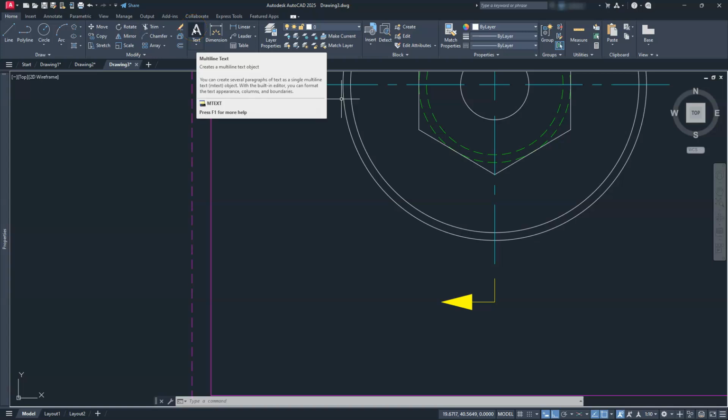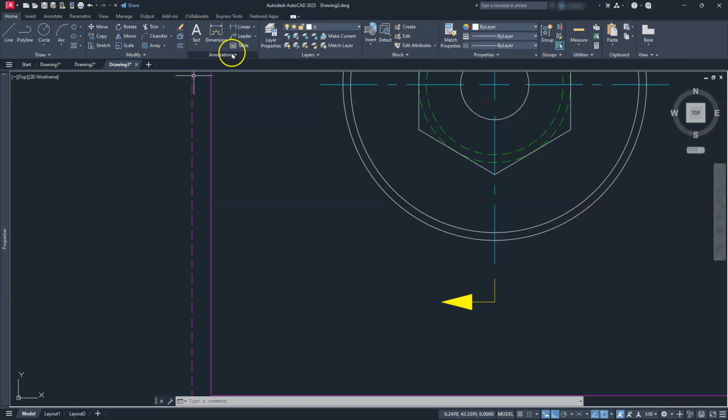Now, if I want this to be automated a little bit, we can use an annotation text. And let's go ahead and use that. So I'll go to annotation. Then I'll go ahead and use a single line text. It's asking me for a justification. I'm just going to call it a middle right. So MR. Just going to touch that endpoint and track just a little bit away from it.